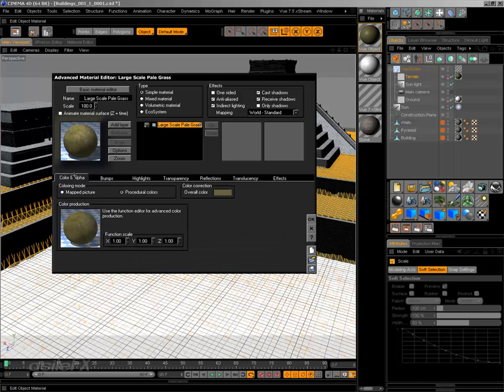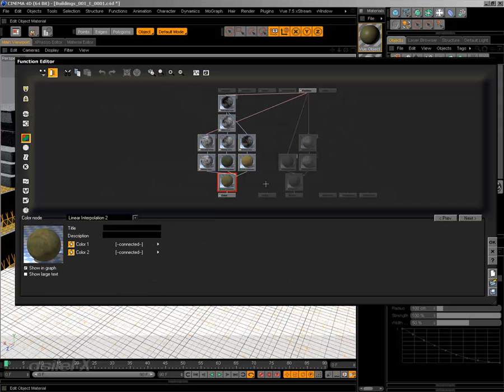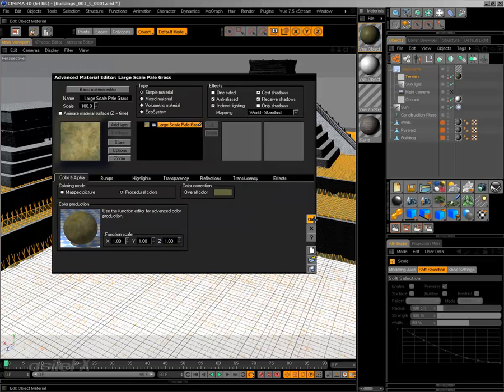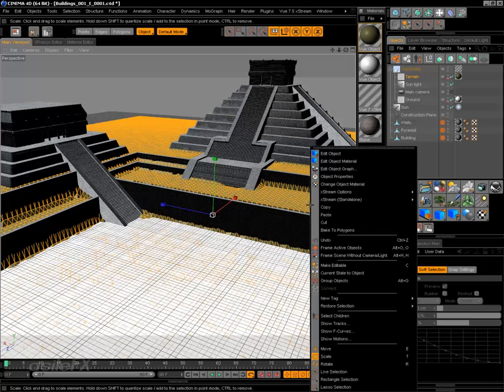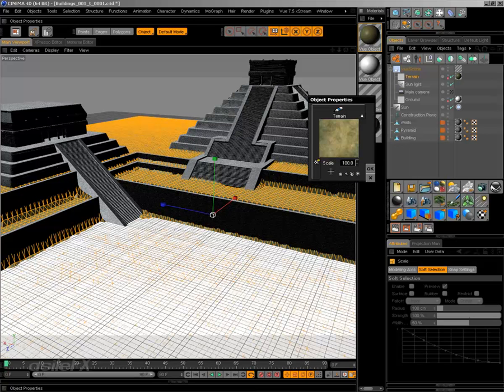And it looks like it may have ignored the alpha automatically, and it did, so that's good. Normally, when there's an object, especially these layers that have built-in alphas, Vue will ask you whether or not you'd like to ignore it, but it looks like that's only going to happen when you're loading a material through the object properties. I'm going to reduce the scale to 50.